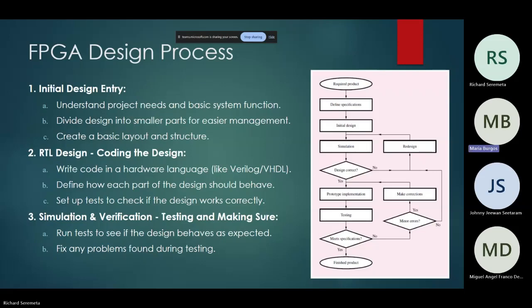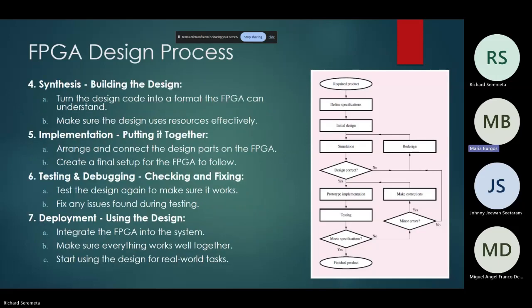This is also where you would fix any other problems found during the testing. The following stage is synthesis, where you would convert the design code into a gate-level netlist that the FPGA can understand using specialized tools, such as Synopsys Design Compiler.